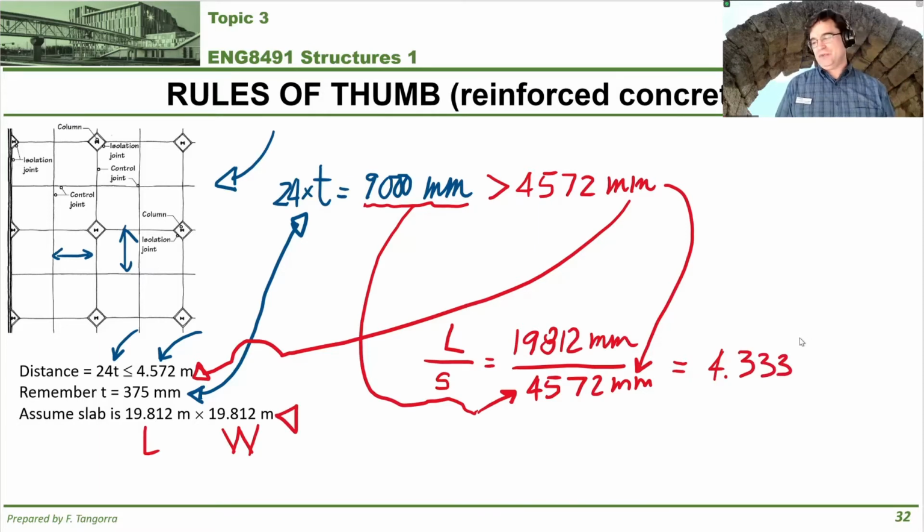No, because you can't use 4.33 spacings, and you want to make anything related to construction and measurements foolproof, right? So what you do is you round it up to 5 spacings, a whole even number, right? You cannot round it down. It's 5 spacings, and then you simply reduce the spacing so that 5 fits an equal number of times into the length or the width.